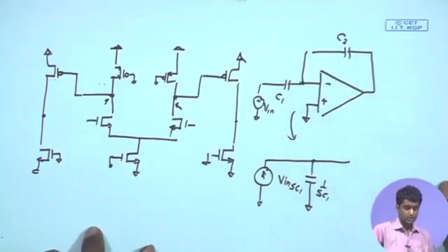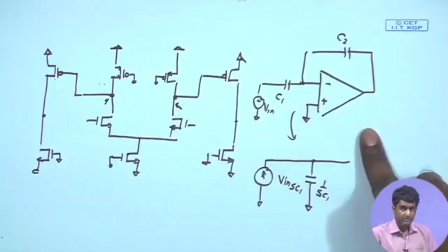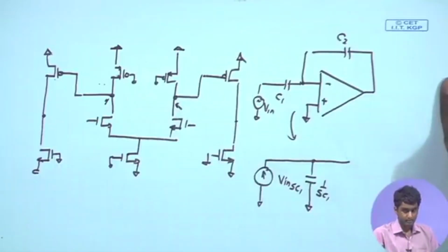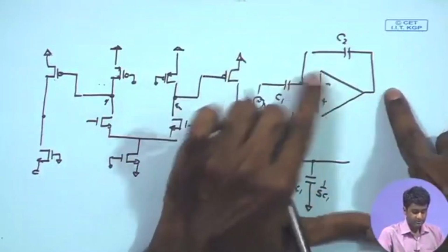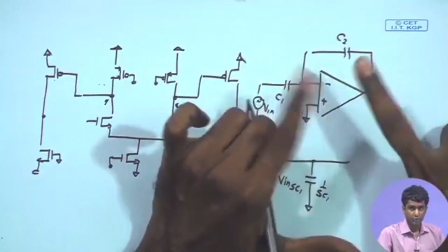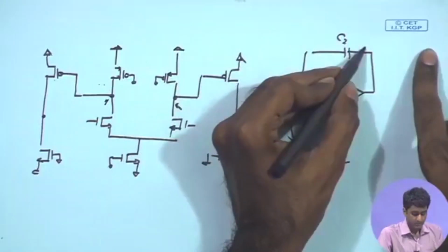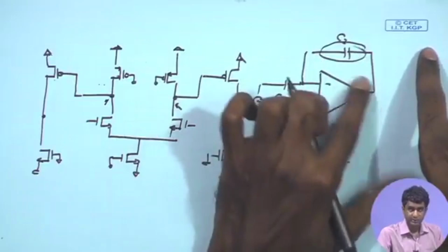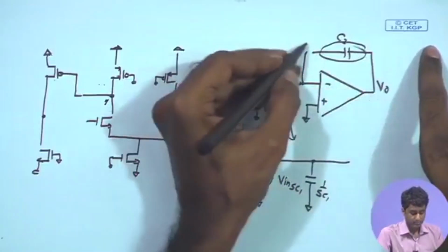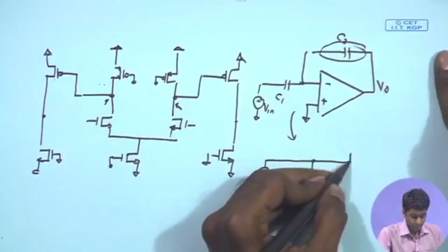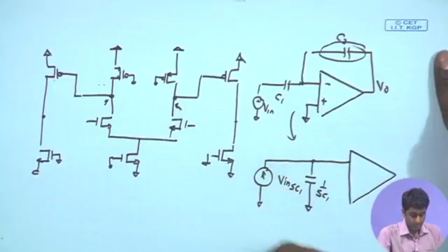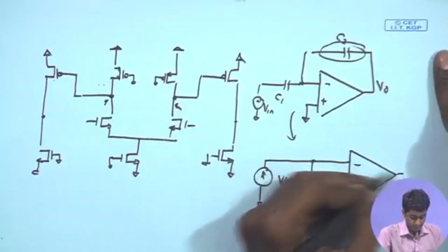Now, for the feedback circuit, if I look at the feedback configuration, this is shunt, and for opening the loop for a shunt configuration, this is my feedback network. This is the feedback element which is sensing the output voltage V out and providing the feedback current. So, let me complete one more step and then open the loop.